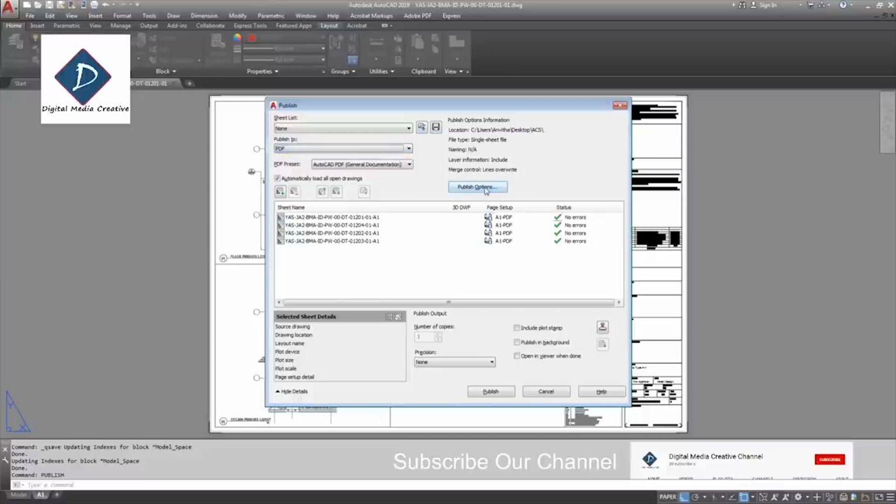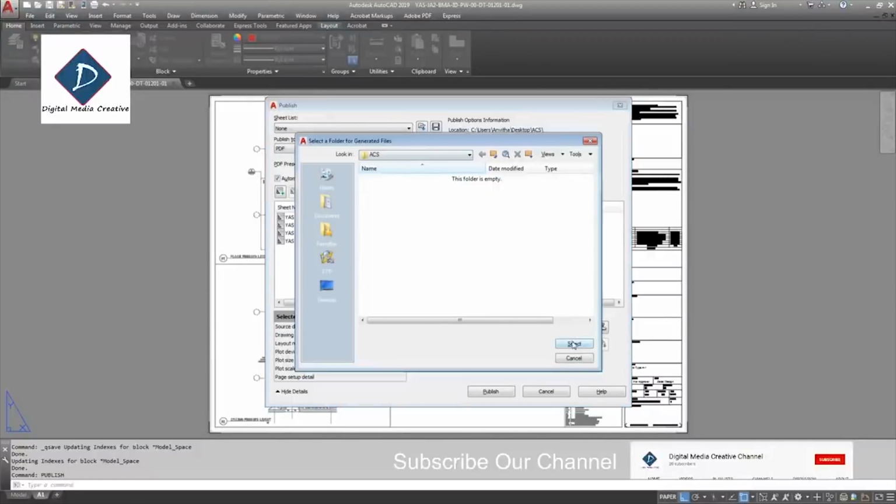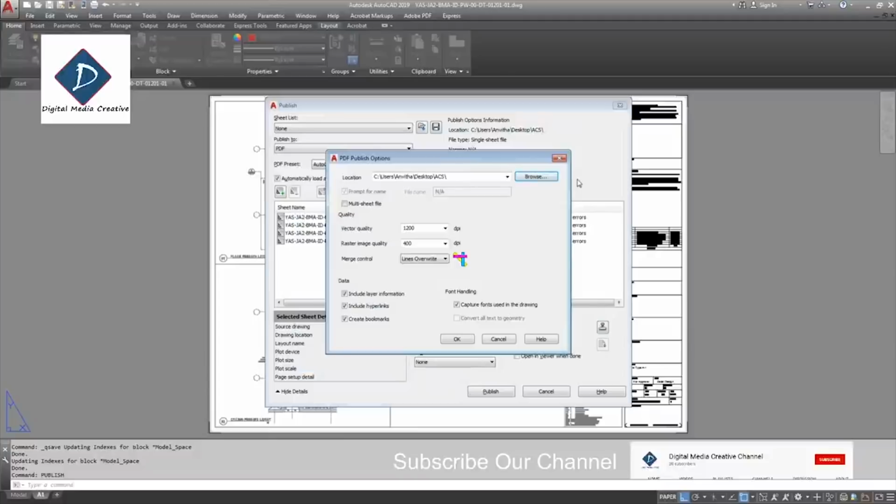Okay, and in publish options, you need to click the location. You can say where you want to save. Okay, and you can see one here, multi-sheet file. Okay, so the thing is, if it's ticked, all the PDFs which we are exporting will come in one file. It will be a binded one, combined. Okay, so if it's unticked, it will be single, everything separate.